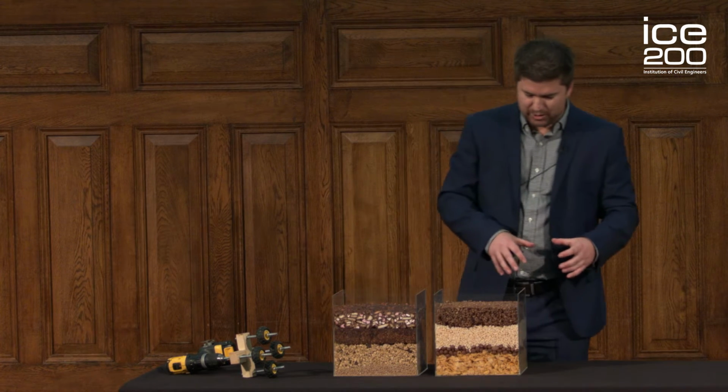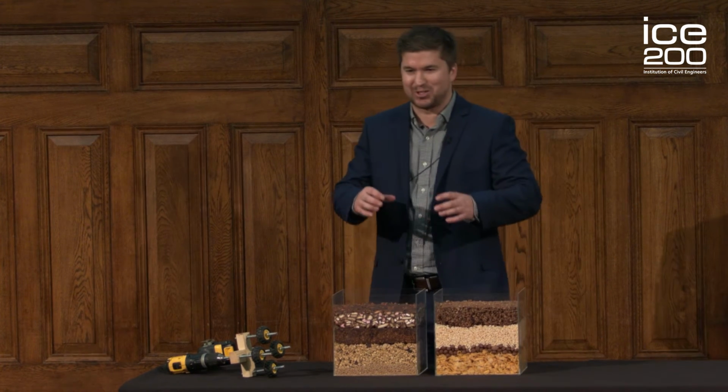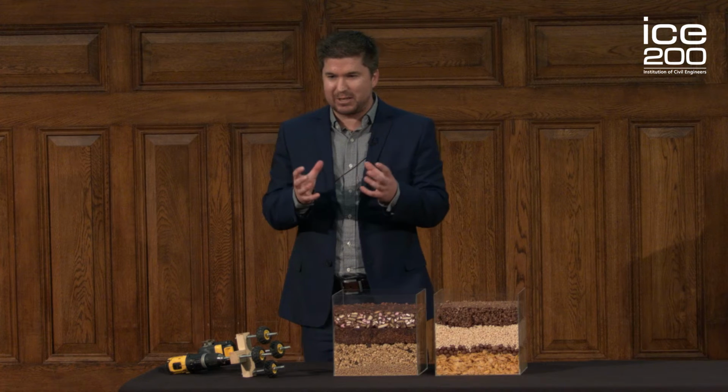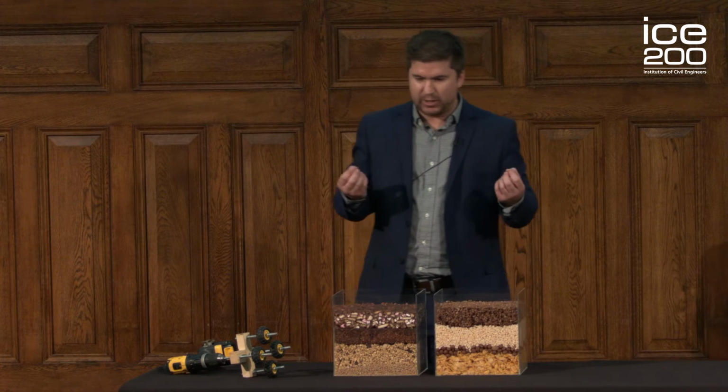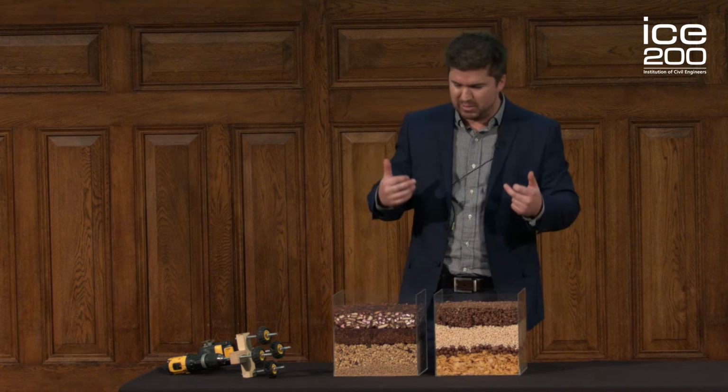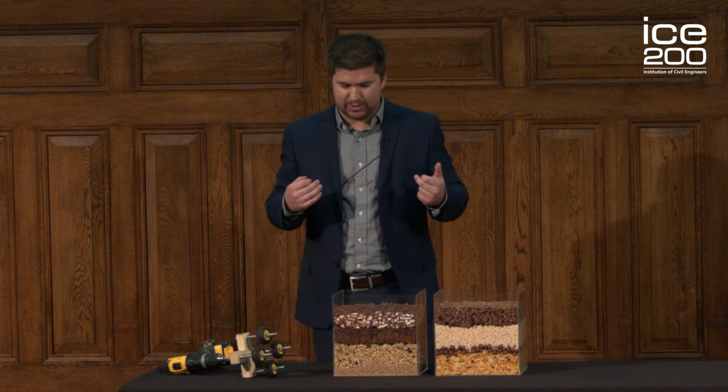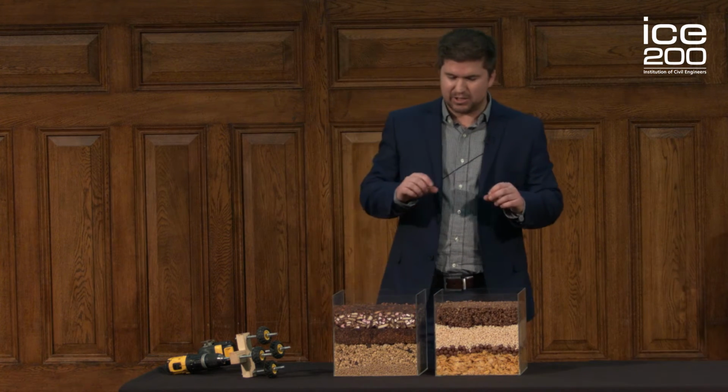What you wouldn't want is something like the cocoa rocks, if you've ever come across those, which are very rounded and all the same size. So there's poor tessellation and lots of voids in between those. So you get what we call migration of fines into that layer, which again means the overlying layers settle down into it. The next layer is the subbase.